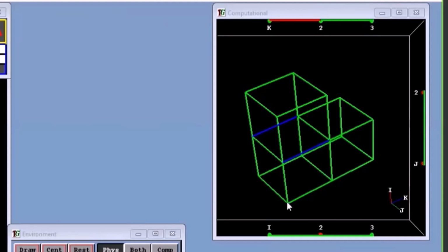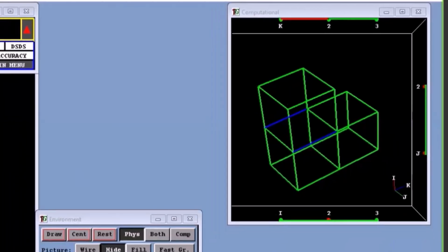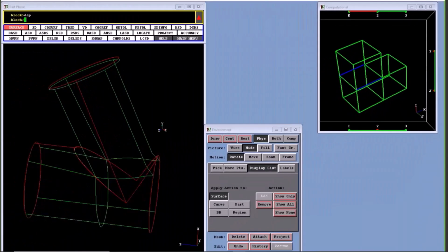In a block structure, we have corners to blocks, and they can be controlled in 3 different directions because there are 3 different faces that meet at that corner. We call the corners of the blocks vertices. Then we have edges that connect one vertex to another. And then we have faces which are formed by nodes surrounded by 4 edges.